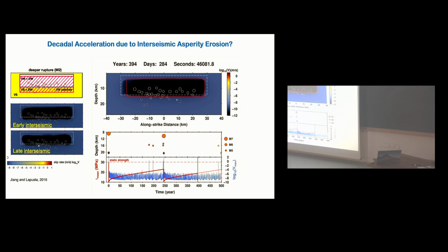So there might be more going on there, but the Hayward fault is just the opposite. And we did look at models of viscoelastic relaxation from 1906 and 1989, models by Fred Pollitz. Those would produce the opposite change in creep rate. They wouldn't accelerate the fault now, they would actually lead to a decay of slip rate.